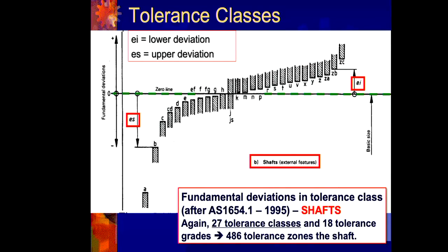For the shaft, tolerancing, same essential process, except lowercase letters corresponding to, in this case, maximum material condition for A, and for a shaft up there, we've got our Z, we've got our shaft, and our shaft can be bigger, so that's our least material condition for Z there.